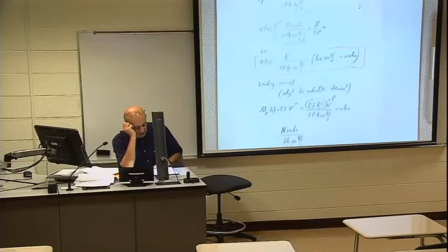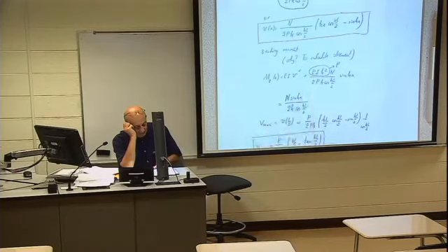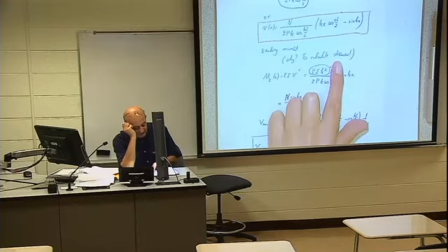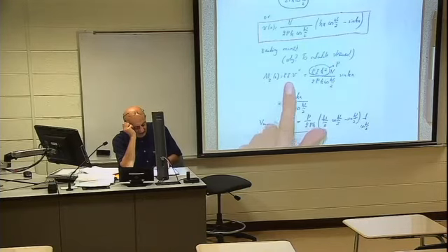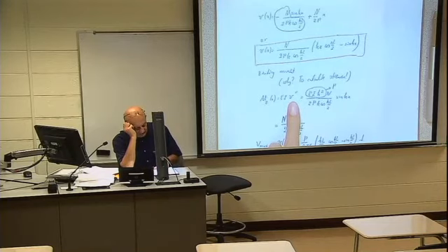And bending moment, again to calculate stress. Mz equals EI v double prime. So the second derivative. The second derivative will be EI times k squared. But EIk squared is P, so n over 2Pk cosine kL over 2 times sine kx.